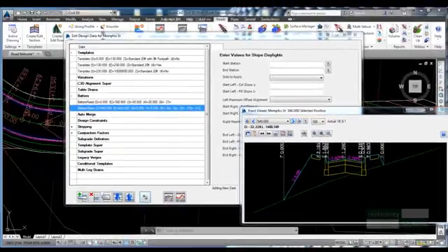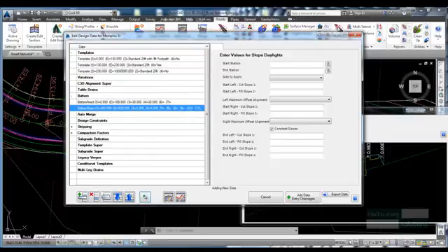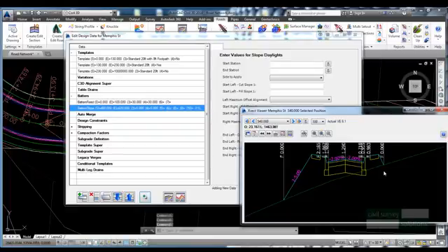Next, we will apply conditional two-section batters. This is a simple logical batter which creates a two-section batter condition. Designers specify offsets relative to the center line to an offset, normally the property boundary, and allow for two slope conditions, depending on whether the start of the section is in cut or fill. The second segment then batters from the offset to the sampled surface at a user-defined cut and fill slope.